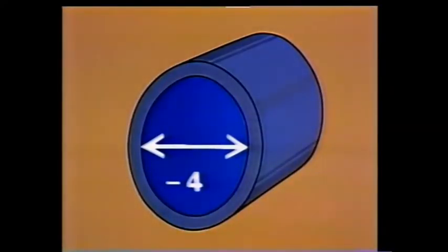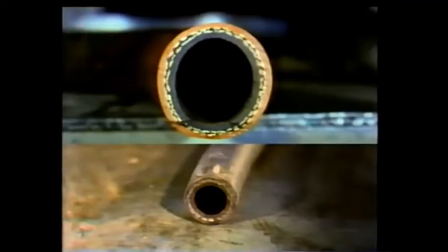It is written with the dash and then the 4. By using the dash system, you can match and connect a hose with a pipe or tube and be assured that the inside diameter of each will be the same, thus ensuring an even flow through the two lines when they're fitted together. Flexible hosing comes in a variety of sizes up to about 24 inches.